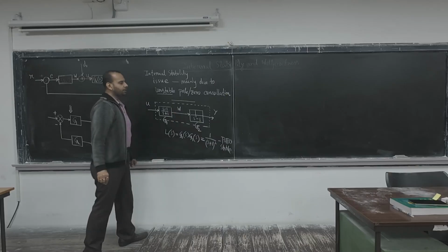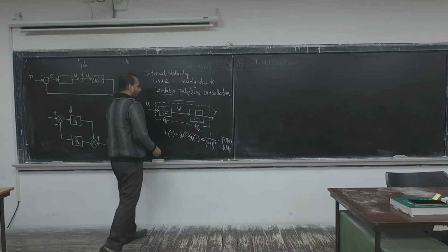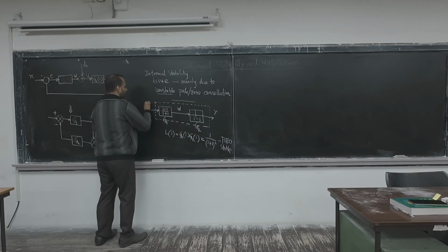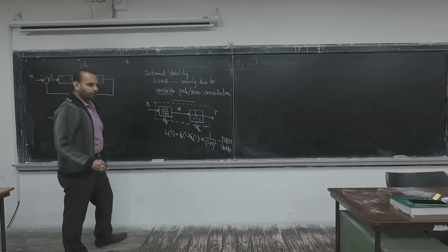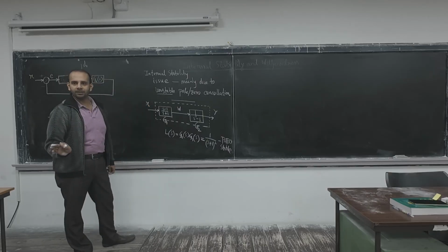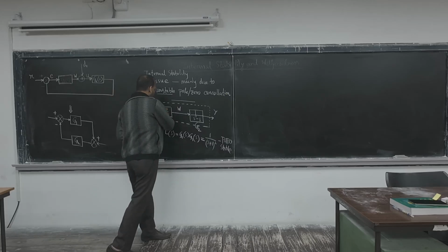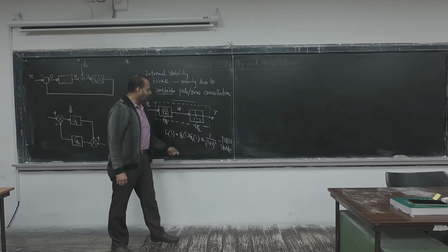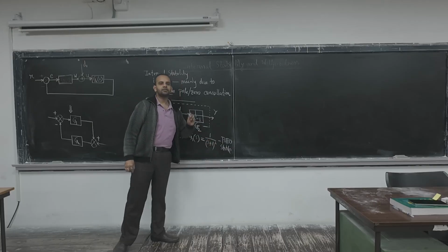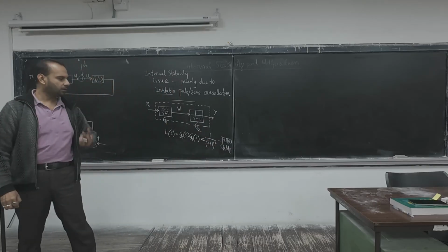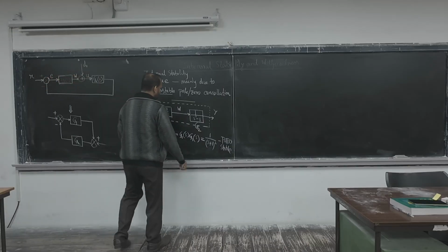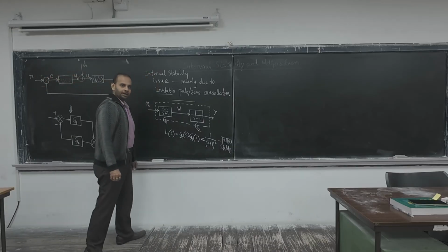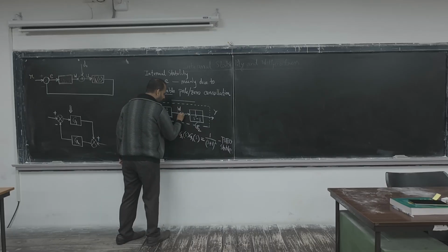So this example we already took last day, where you could see that if we consider only this channel, if you had a single system, then what is your solution? R, right? If we consider only this channel, R to X, then absolutely there is no problem, because mathematically at least the pole zero will get cancelled out, and we will be left with 1 by s plus 1 whole square. So no doubt it's a BIBO-stable system. But the problem is when you think about another channel, also the same. Consider that here is a disturbance, because now you have this interconnection. That was a difficulty, right?